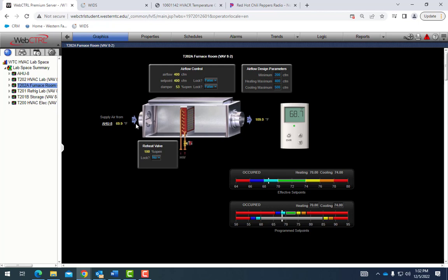So there'll be a damper rod sticking out of the side, and most of those VAV controllers will have an actuator built onto them so they can control that. Here's our hot water coil. As you can see right now, it's calling for 100% open. So we're going to send some on-off signals, some modulating signals. We may send it 0 to 10 volts to control this hot water coil, so we can fully close it, fully open it, put it at 50%, things like that. There are some pulse ones out there. Just something we'll get to see a lot of.